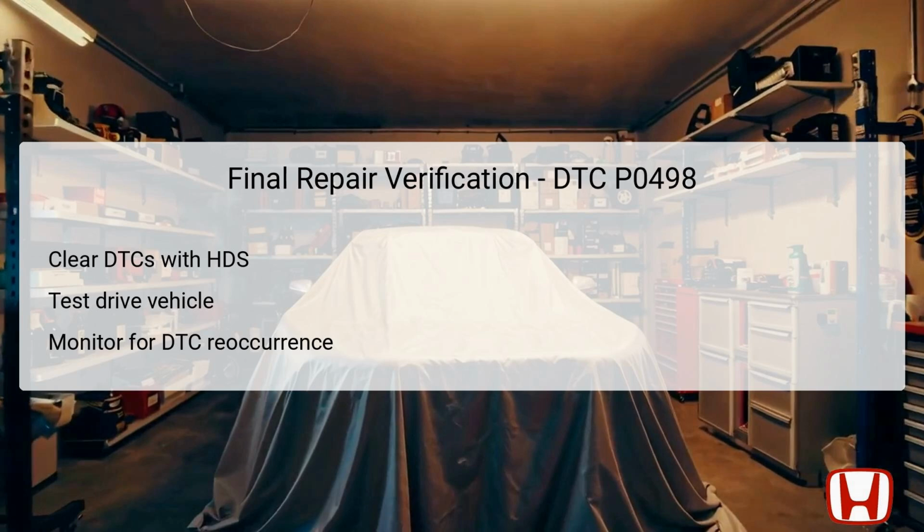After the test drive, use the HDS to monitor for any reoccurrence of DTC P0498. This final step is critical as it ensures that not only has the original issue been addressed, but also verifies that all components and connections are functioning optimally. If the DTC does not return, this points to a successful repair, while reappearance suggests further investigation may be required.